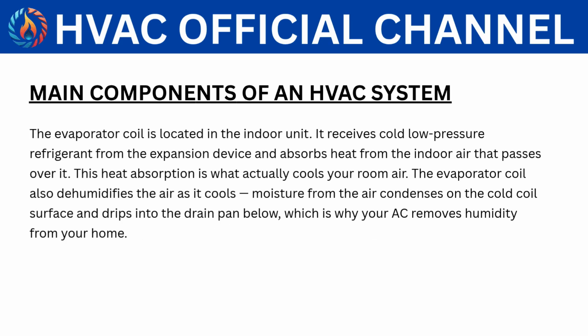The evaporator coil is located in the indoor unit. It receives cold, low-pressure refrigerant from the expansion device and absorbs heat from the indoor air that passes over it. This heat absorption is what actually cools your room air. The evaporator coil also dehumidifies the air as it cools. Moisture from the air condenses on the cold coil surface and drips into the drain pan below, which is why your AC removes humidity from your home.